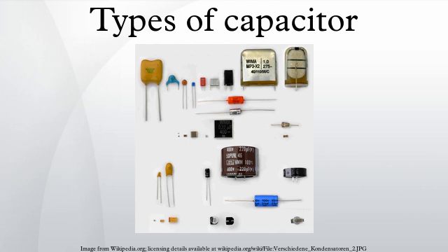AC current. An AC load only can be applied to a non-polarized capacitor. Capacitors for AC applications are primarily film capacitors, metallized paper capacitors, ceramic capacitors and bipolar electrolytic capacitors. The rated AC load for an AC capacitor is the maximum sinusoidal effective AC current which may be applied continuously to a capacitor within the specified temperature range.